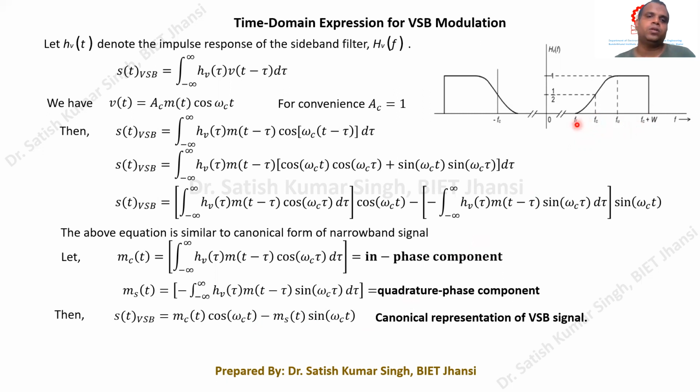Therefore the bandwidth requirement will be a little greater than 4.5 megahertz. Practically, we take 6 megahertz as the bandwidth of the video signal. We also send the audio signal along with the video signal, because the transmission contains both video and audio information. So for transmission of the video signal, we use VSB modulation.